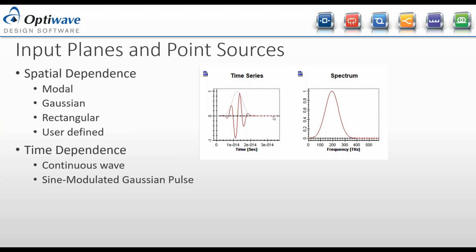The reason why this is so fundamental in FDTD is that if you do the Fourier transform of a Gaussian pulse in time, you'll get a finite width Gaussian pulse in the frequency domain, right? So we'll see this is actually that calculation done on this plot on the right, and this shows you that this pulse has a pretty wide bandwidth. So by doing one time domain simulation, you can get the results for a whole load of frequencies.